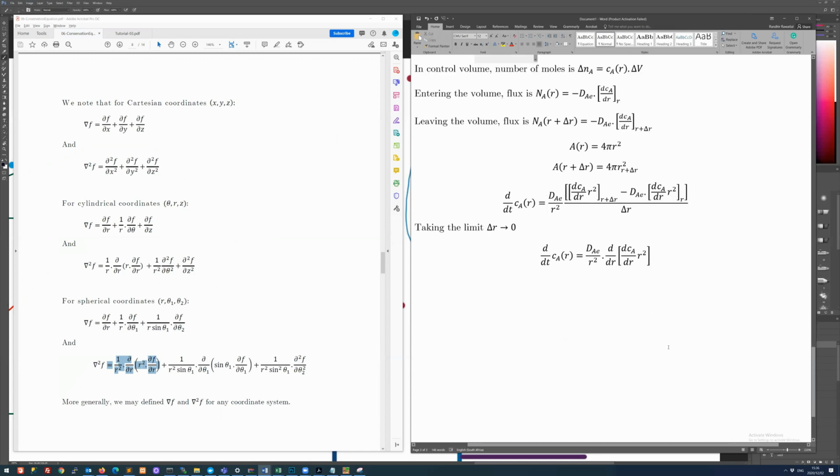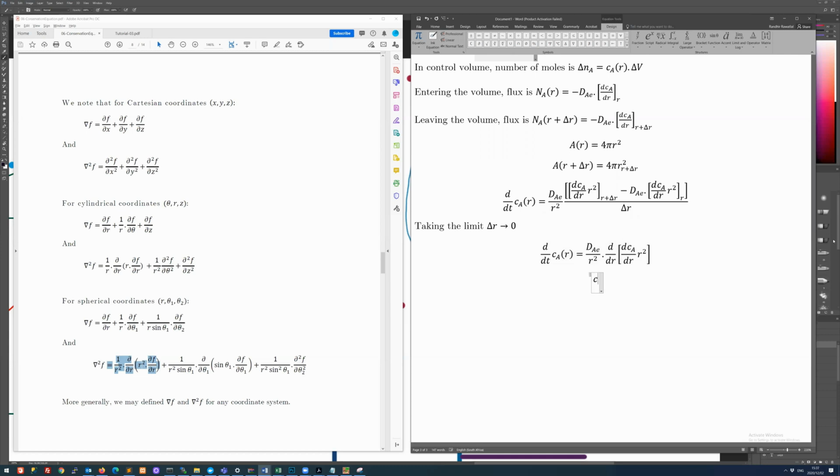The other thing we need to do is derive the boundary conditions here. Number one, let's say the particles entered with no sulfur dioxide in them, right? The whole point is we are trying to absorb sulfur dioxide into the particles. That means the particles are entering without sulfur dioxide. So at t equals 0, they enter, and at all radial positions, there's none of the sulfur dioxide. So that's our initial condition.